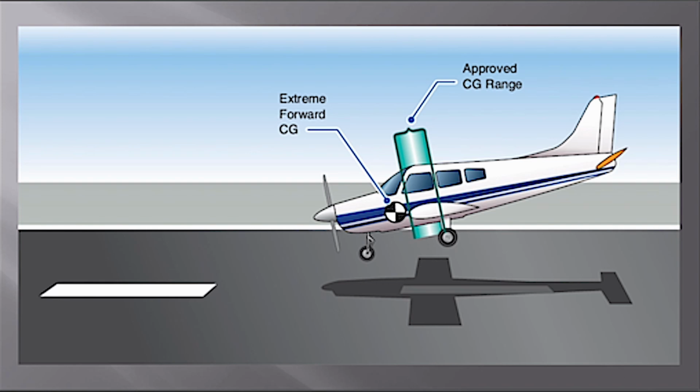If you're outside your CG limit, you break the nose gear. You just don't have enough force back here with this elevator to increase that pitch angle. You just don't, okay?